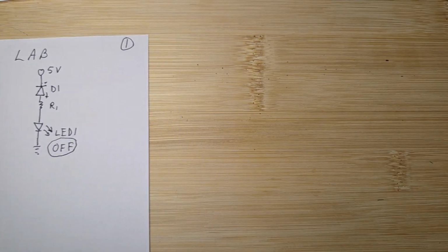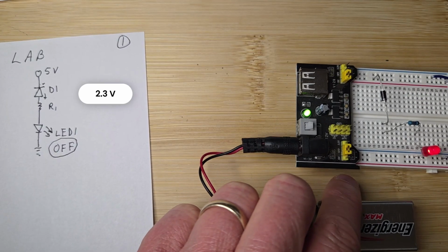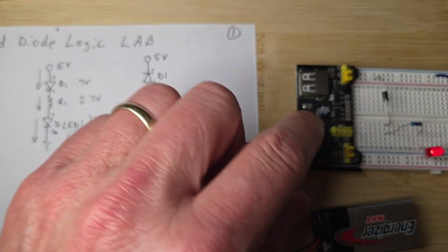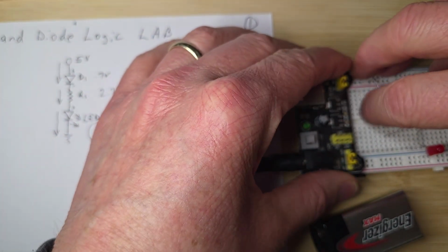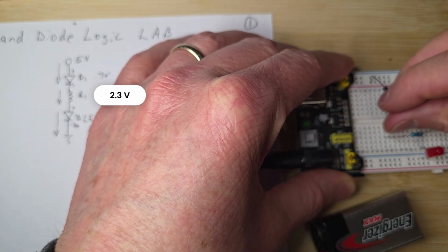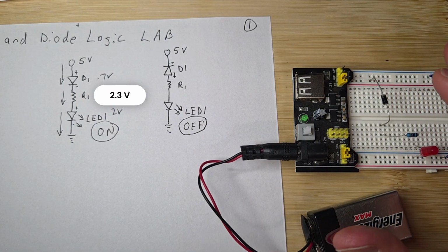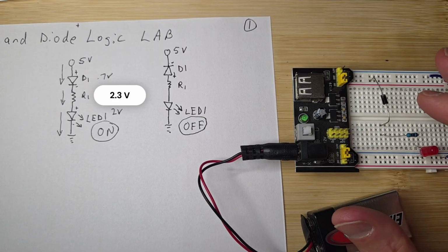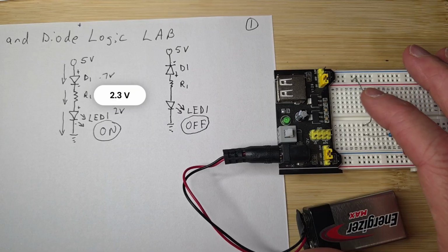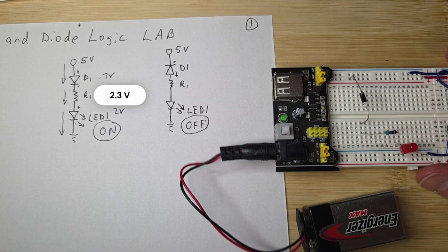Let me move this over here where we don't confuse anybody. Okay, now I'm going to turn this off, and then reverse the diode. These diodes have ratings; I think this one's really high, you can go to like 50 volts in reverse mode. That's something to always consider, because it's not infinite. If I put 100 volts on this thing, it's going to blow up the diode. It can't handle it. But I think this one's good at 50, which is amazing.